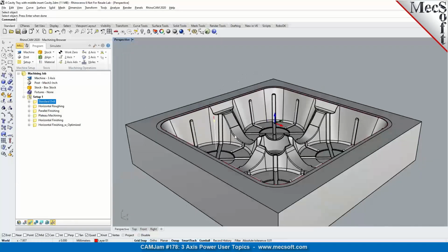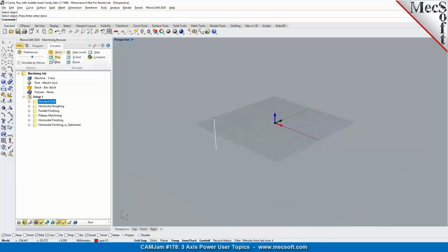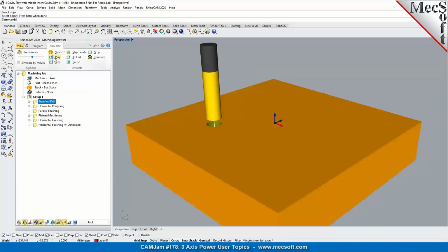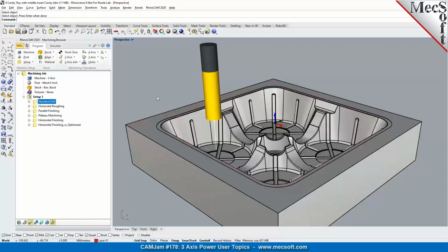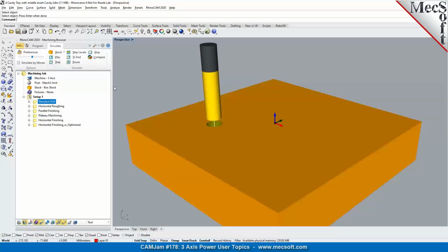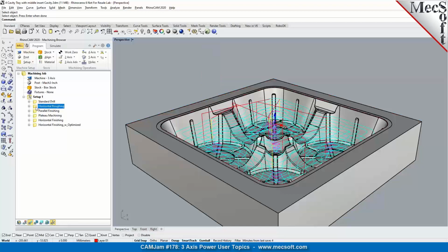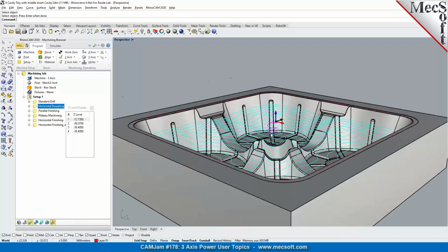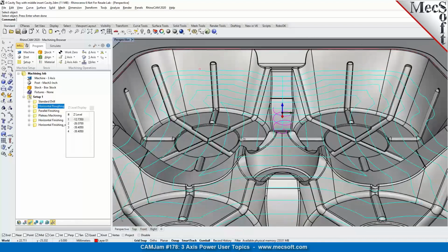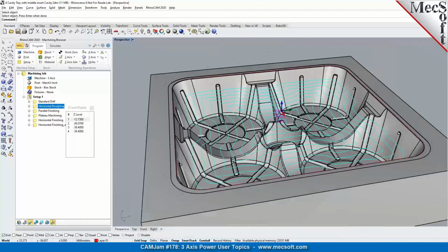So I'm drilling down 40 millimeters deep with an end mill, or it could be with a drill bit. Once we've done the drilling process, we would like the cutter to enter at this pre-drill location at the start of the roughing operation. If you generate a horizontal roughing operation, the roughing toolpath automatically figures out the best possible location for the entry or your ramp motion.